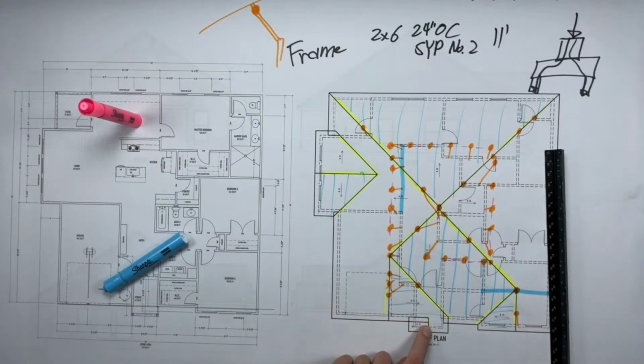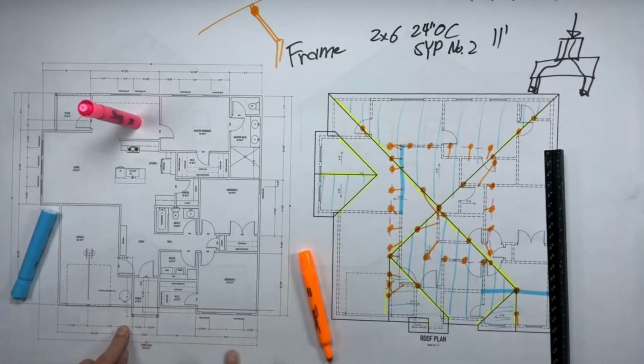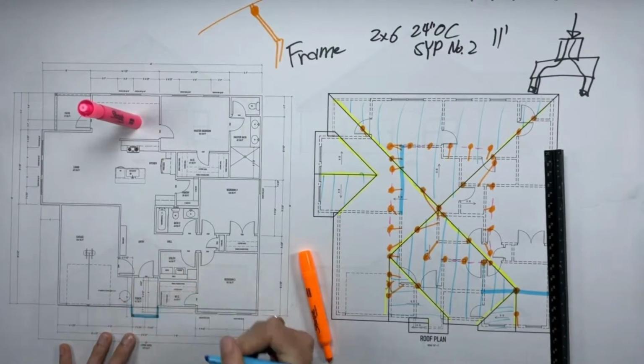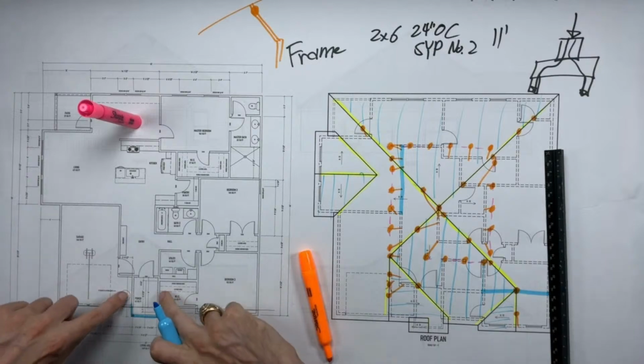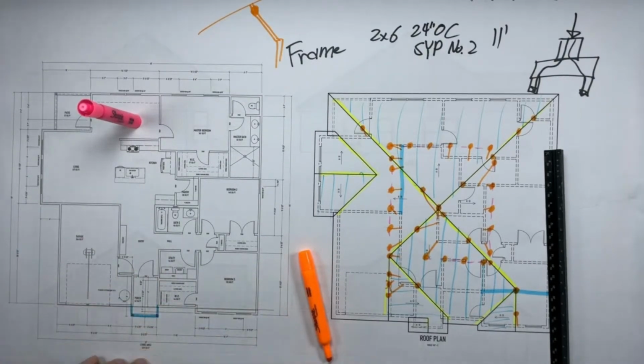Let's talk about this little guy. What's happening in here? Well, right here, the porch comes out. There's a beam that's big in the front of this thing. So let's highlight that so we can see what's going on first. So those are beams, and the top of the beam is in line with the 10-foot plate height of the wall, and it comes out and it makes that box. And that's what shapes the start of this roof.